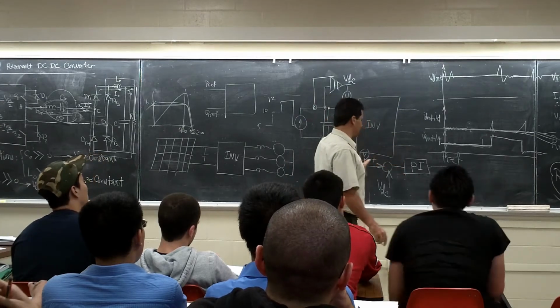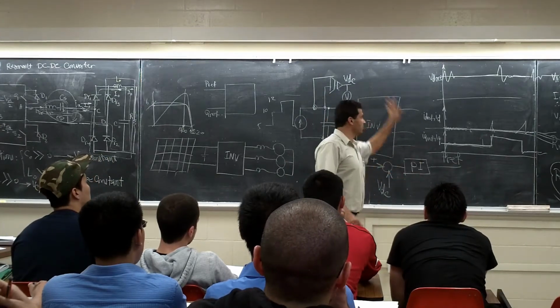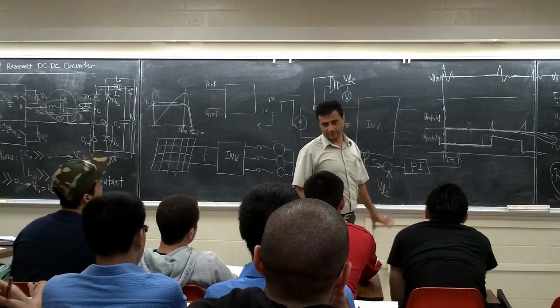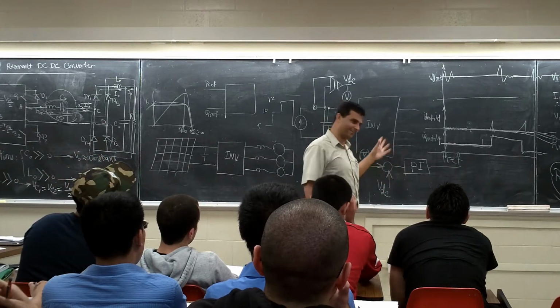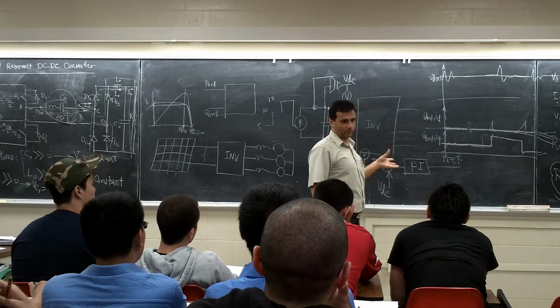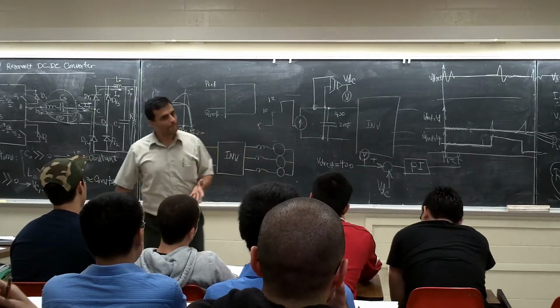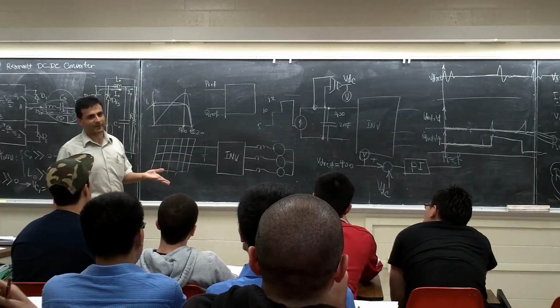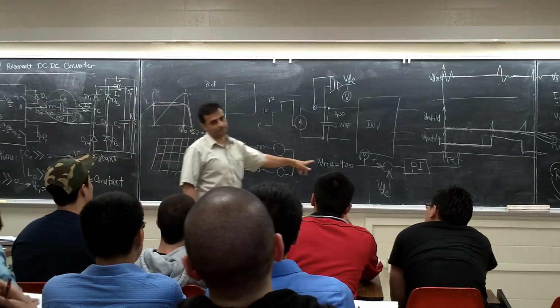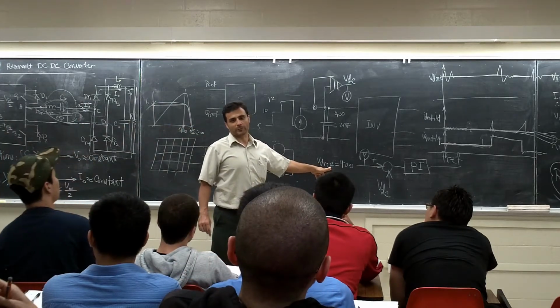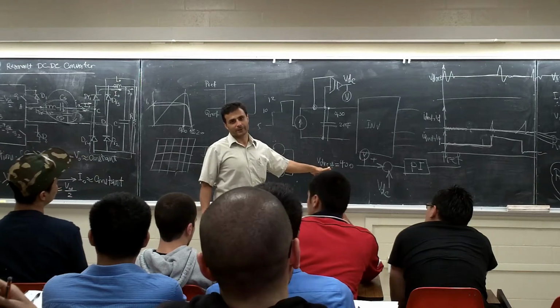So you do this. You set this PI, you get good results, right? You're 90% done, 80% done, with your phase 4. What's the next step? MPPT. MPPT algorithm. This VRF I put here should come from the MPPT loop, right?